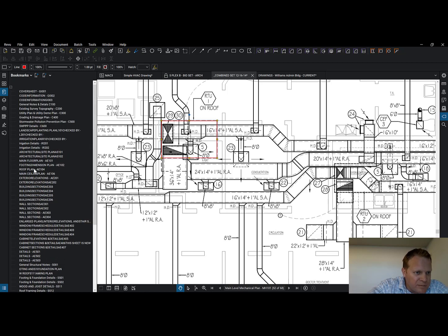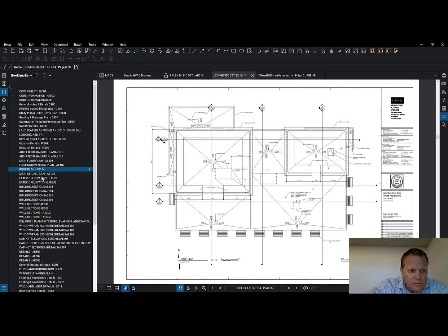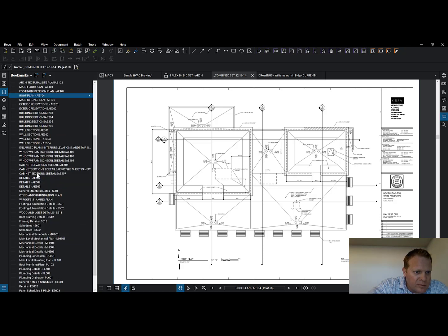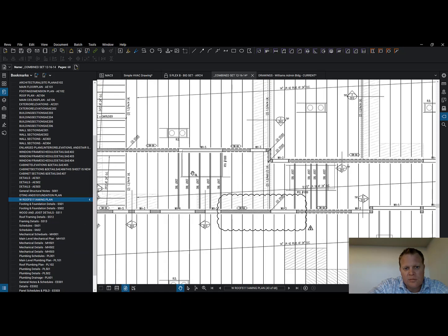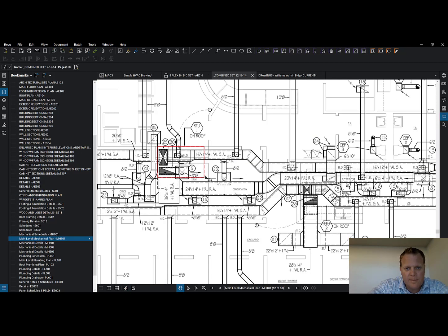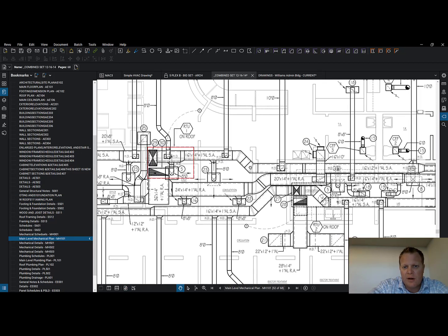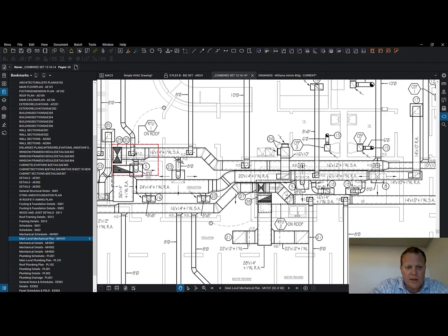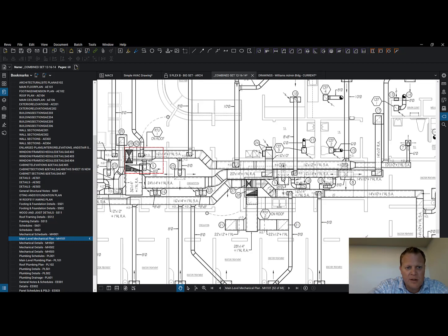So back to that roof. Do you remember that roof plan? Roof framing plan. There's no way there's 36 inches between those. So for sure we cannot just frame this. We've got a rooftop unit up right here that has a 36-inch wide opening in it for all right, now we've got to figure out, so what is this? This is the supply side, that's the return side.